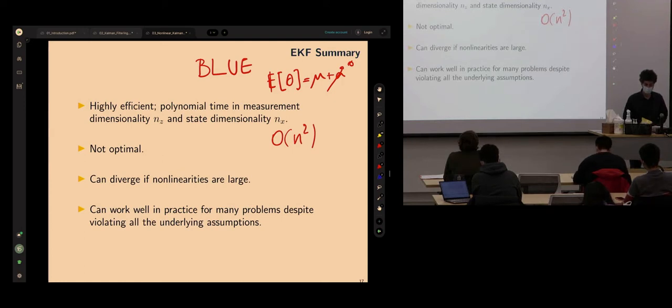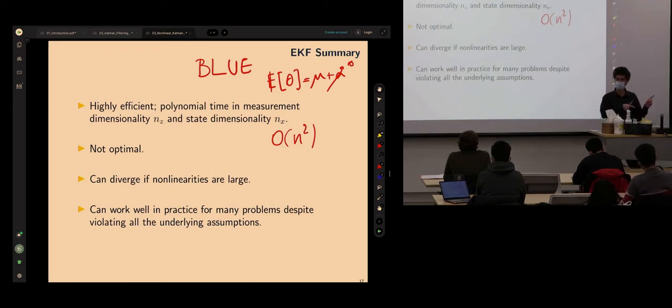One of them is, for example, SLAM. If you do EKF SLAM with a lot of landmarks, that's a concern because if you do wrong data association, assigning a detected landmark to the wrong previously seen landmark, then the filter can diverge. You're injecting outliers, wrong information, into the estimator. And the EKF is very brittle with respect to that because you linearize, it's a filter, you move on.